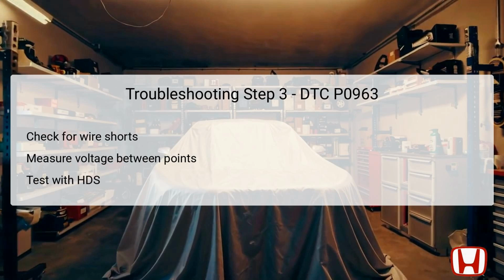The third troubleshooting step involves checking for any shorts in the wiring, specifically from the DRLS line to power. First, ensure the vehicle is in off/lock mode. Jump the SCS service check signal line using the HDS to prepare the system for testing. Next, disconnect the PCM connector C and the solenoid wire harness 8P connector.